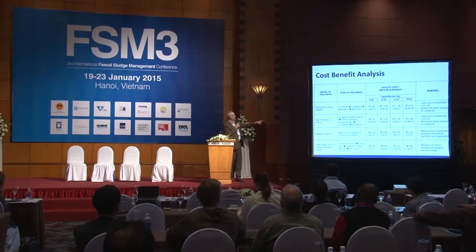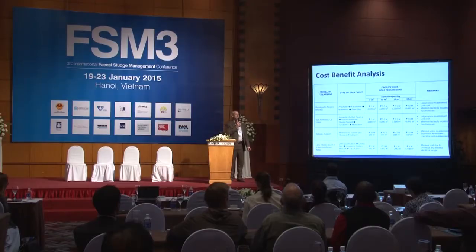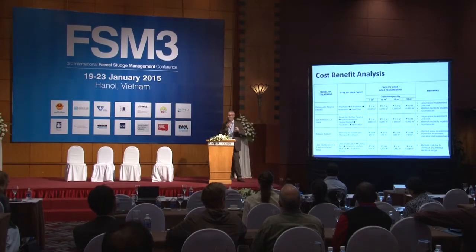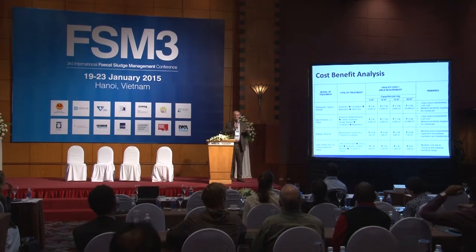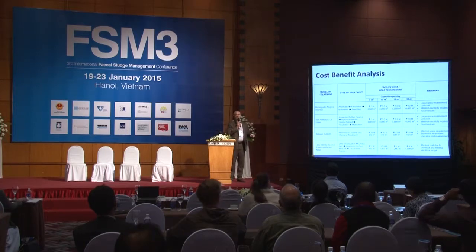But what was really nice was that with the lime stabilization, the cost is affordable. Well, it's the least expensive at 2 million pesos for, say, the 5 cubic meter. But if you compare the amount of land required for the system, those two factors, the low cost and the small footprint, make the technology attractive, at least to the point that it's worth looking at a little bit further.